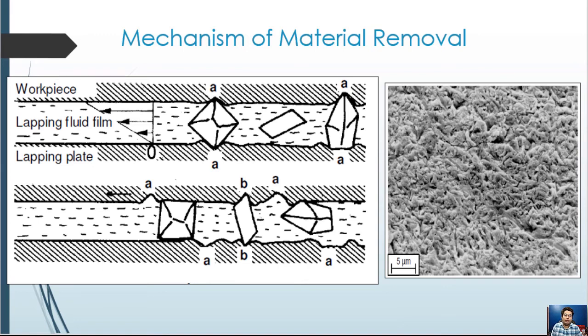Now, speaking about the mechanism of material removal in lapping, the work surface rubs against the workpiece surface to be processed. Machining is achieved by means of insertion of lapping slurry, lapping grains and the fluid into the working gap between the machining disc and the workpiece. In the process, loose grains are added either continually or intermittently. The existent dependencies and interdependencies are complex.